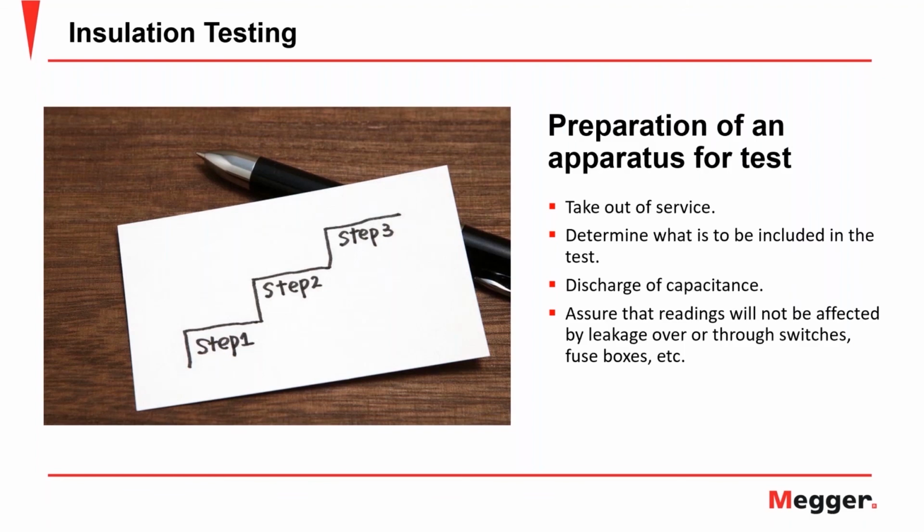This is very important at the end of the test. This is your primary safety feature with doing an insulation test. What goes up must come down. Since this is a DC test, and we've already mentioned charging up the test item, charging the capacitance and charging the absorption current in the insulating material itself, that can be dangerous.